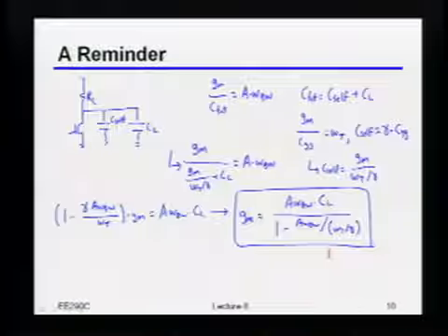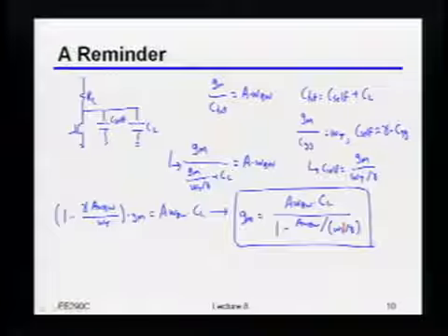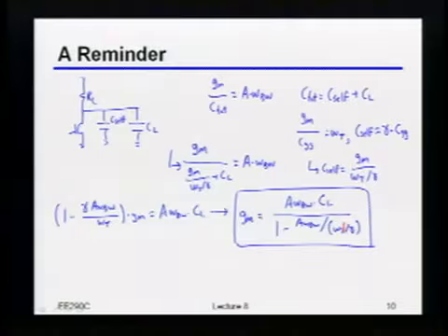So this is basically telling you that no matter how much GM you spend, if you tried to get something that has higher bandwidth than that intrinsic bandwidth of the device, not going to happen, right? Not only that, it actually tells you, depending upon how close to that intrinsic bandwidth you're operating, exactly how much extra power you have to spend due to the fact that the device doesn't have infinite bandwidth, right? So in particular, how close to the intrinsic bandwidth of the device do I have to be in order for me to spend 2 times what I fundamentally would have had to spend anyways with a perfect device?